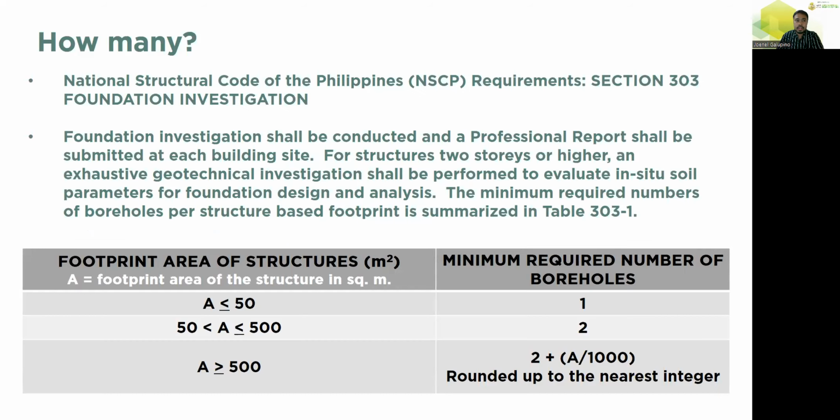So our next question is, how many? As per our National Structural Code of the Philippines, or NSCP, Requirements Section 303 Foundation Investigation, foundation investigation shall be conducted and a professional report shall be submitted at each building site. For structures 2 stories or higher, an exhaustive geotechnical investigation shall be performed to evaluate in situ soil parameters for foundation design and analysis. The minimum required number of boreholes per structure-based footprint is summarized in Table 303-1.